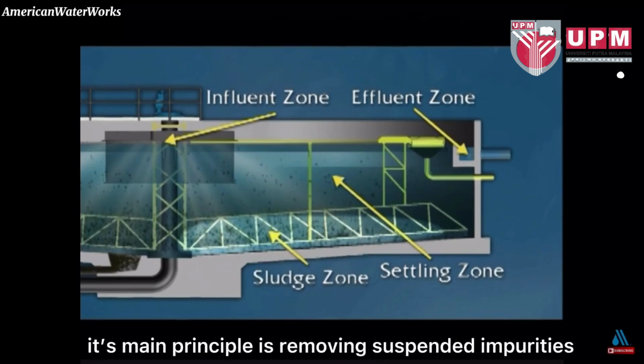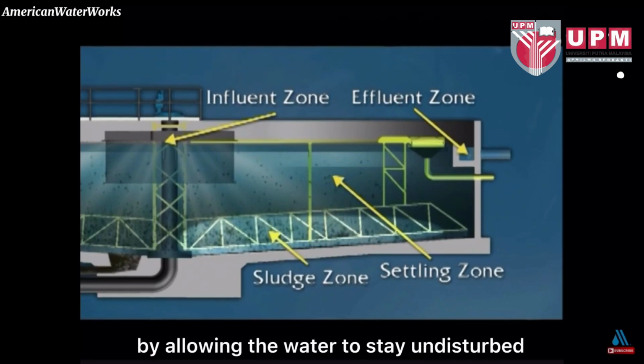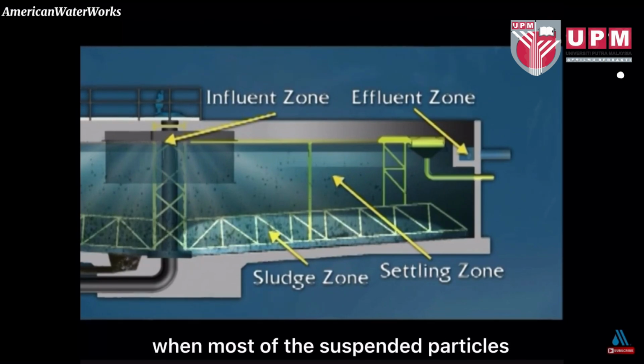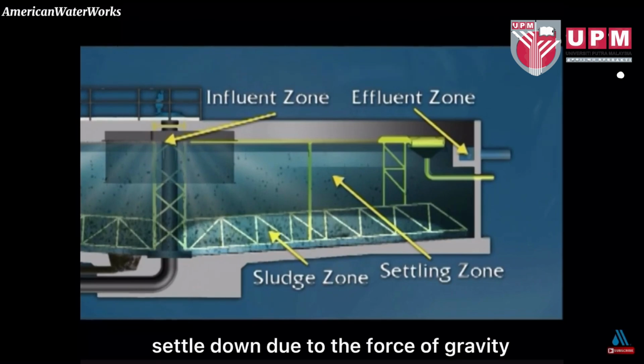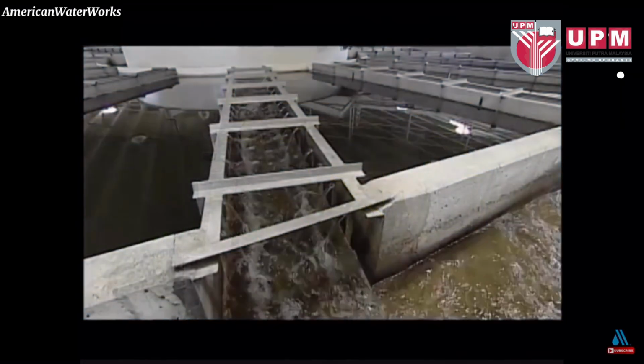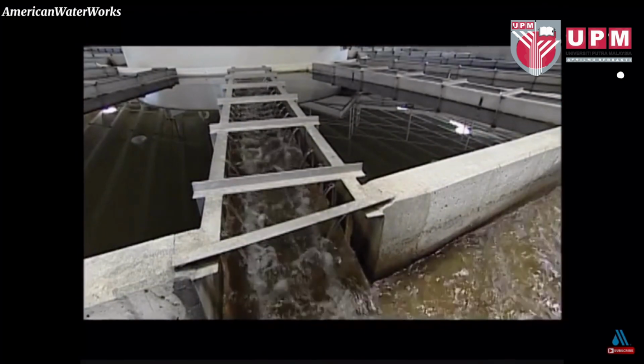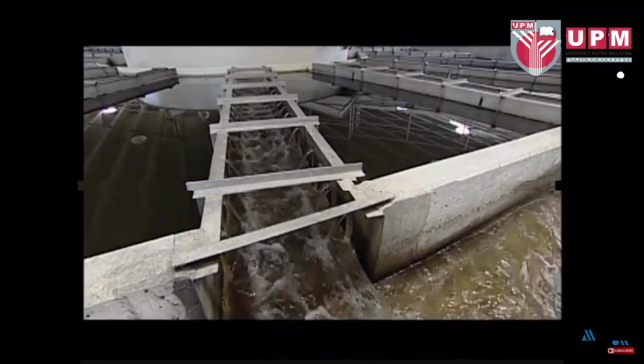Its main principle is removing suspended impurities by allowing the water to stay undisturbed for some time in large tanks, when most of the suspended particles settle down due to the force of gravity. The clear water can be taken out from the tank with the help of pumps.